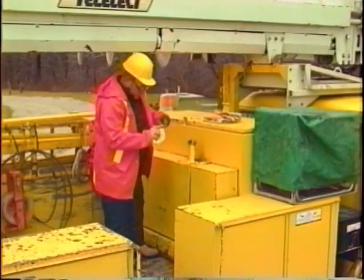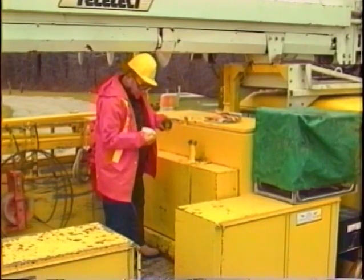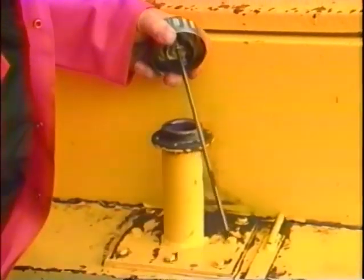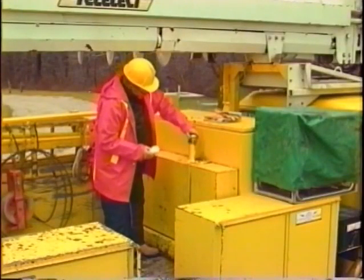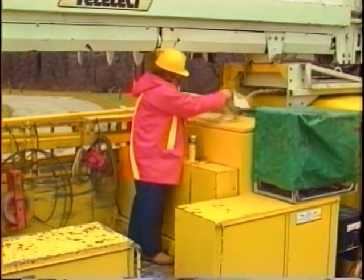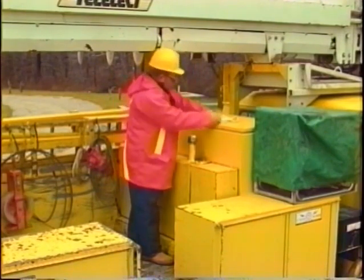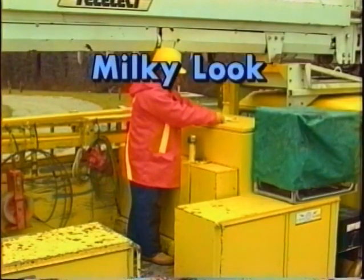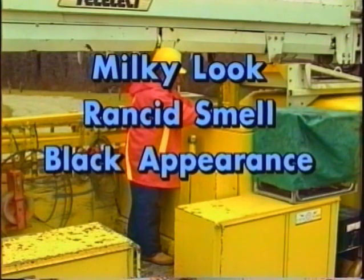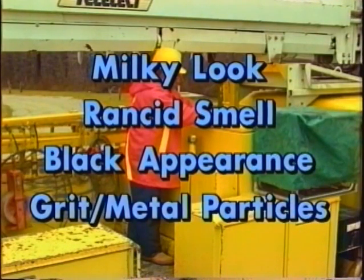Now it's time to check the condition of the hydraulic fluid. The importance of this step cannot be overstated. One manufacturer claims that as many as 70% of all service problems could be avoided by more frequent fluid changes. Some things to look for are a milky look indicating the presence of water, a strong rancid odor giving evidence of overheating, a black appearance, or the presence of grit or metal particles.